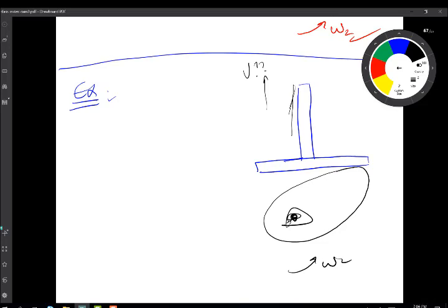So now, again, let's count our links. The cam is link number 2. The follower is link number 3, and nothing between them. So I have 3 links because I have a higher pair. Remember, the minimum number of links you can run in a planar thing is 3 if you don't have higher pairs. But since I have a higher pair here, then I have 3 links and will constitute a linkage without a problem.